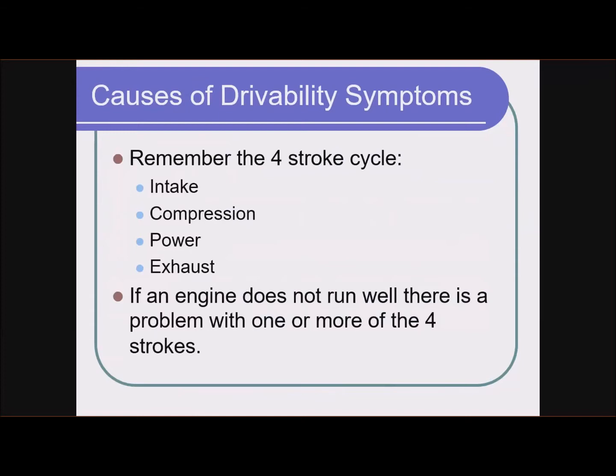Either it's failing to take in a good mixture of air and fuel in the correct amounts, or it's not compressing it properly, or a problem with the power stroke, but typically you would think ignition, right? Not lighting it correctly, or a problem with the exhaust stroke.